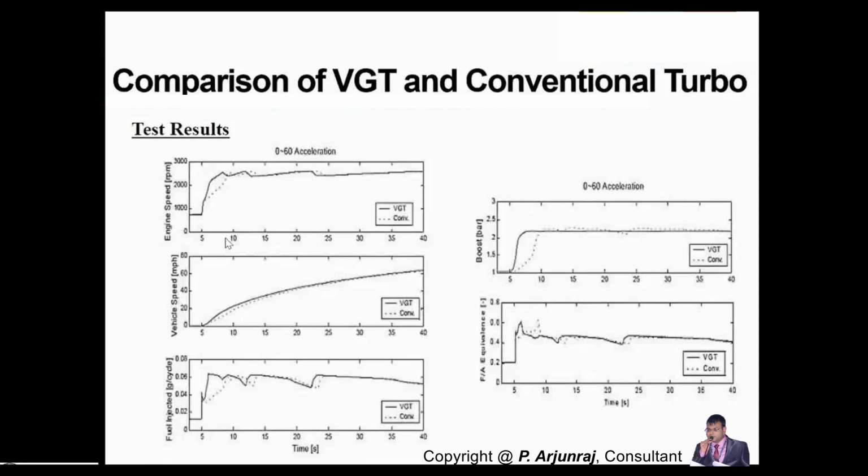At low RPM, the pressure will be lower, so this boosts the pressure basically. With variable geometry, there is an increase in pressure, starting with the boost pressure. You're going to increase the boost pressure at idle RPM, I mean, during the start of the vehicle.